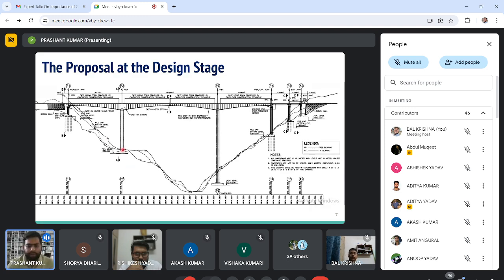You see, we located the foundation at the most plain location. Here I was telling you he has put up a foundation, but we eliminated it. If we have to go with a 90-meter span, a foundation cannot come here. It has to go 90 meters here. Then as I told you, that 248, around 250 meters, was not possible to go directly to D, so we needed an intermediate pier, and that also we needed at location C where the strata was good, and we wanted to hit as plain as possible and as far away from this location.